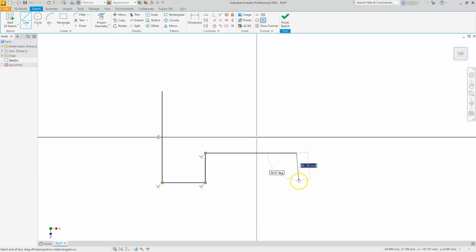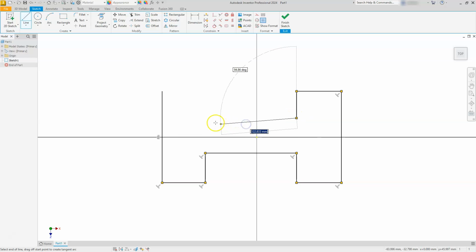In this case, you can leave these in line with each other so they do track off of it, and we will get that collinear effect that's going to happen. And here at the top, I'll wait till I get the dotted lines here. Likewise here. So you see that I am getting all of those collinear snaps, for lack of a better term, or constraints is actually what I was meaning to say. So I'm just taking my time and making sure that I create this eye shape with all of these in line with each other.